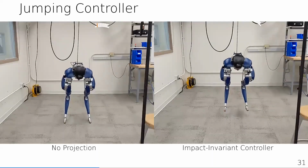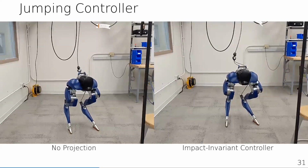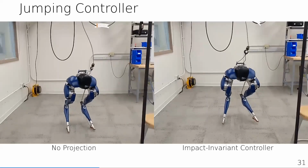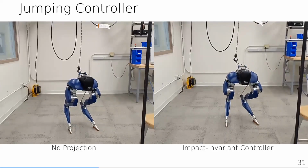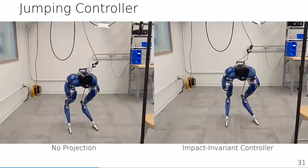We evaluate our method against a default controller without the projection. So left is without the projection, right is our method. And looking at just the impact event, which is where these controllers are different, you can see that the impact invariant controller results in much smoother impacts. Watch it one more time. The one on the left shakes and has a lot of vibrations at impact event due to overreacting due to uncertainty.